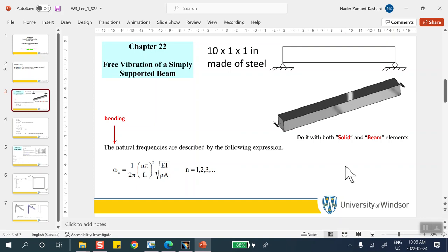It's going to be very tough because the I this way is a lot bigger than the I that way. It's going to be tough. It can also twist; it can vibrate as a torsional vibration. It can do torsional vibration or axial vibration. But the one that's very easy to agitate or to create is bending vibration in the first mode. That's very easy. These numbers are important because you want to avoid them.